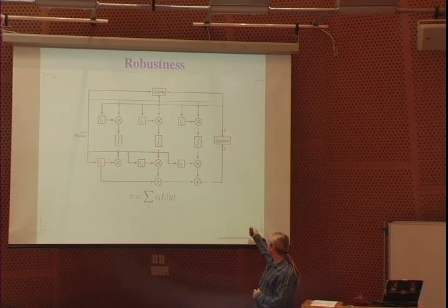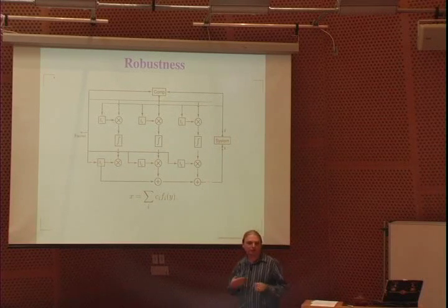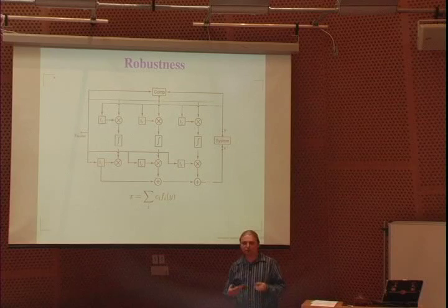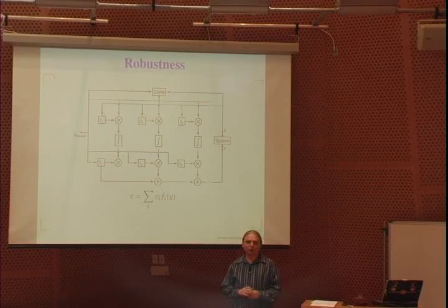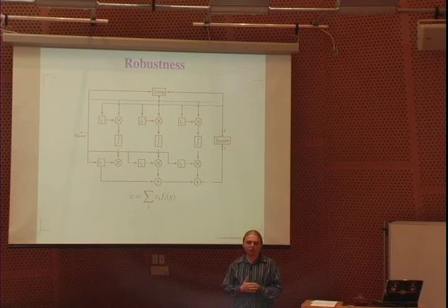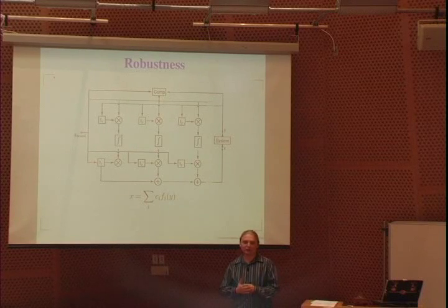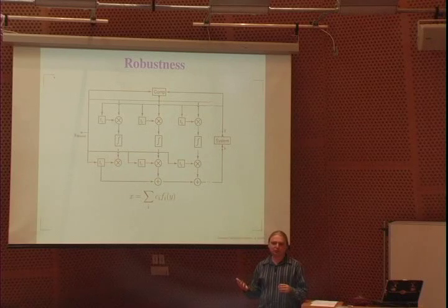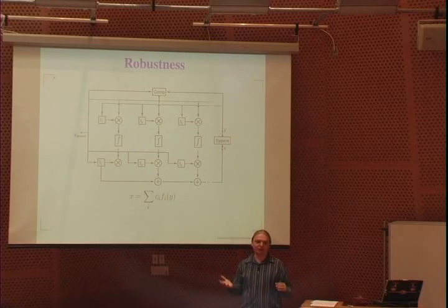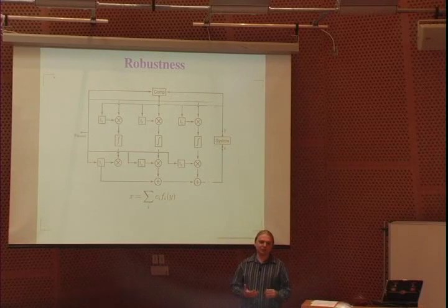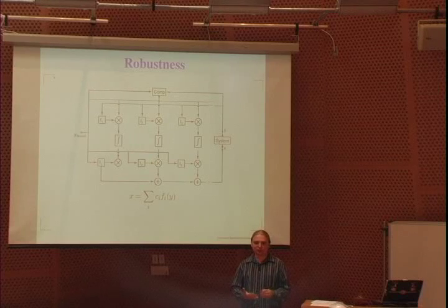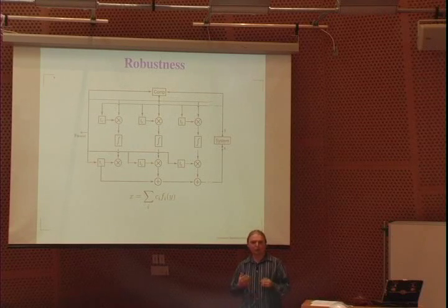They'll just treat that as part of this nonlinearity, and they'll compensate for it, which is a very nice property. In digital circuits, we're coming up with Moore's law to the point where we're expecting devices to fail. So if you look at a device of maybe about 1/10 of a micron, it'll have 150 atoms of dopant in the channel and a standard deviation of 20. As that gets smaller, the number of dopant atoms gets smaller, and we're getting very close to the point where we're expecting some devices to fail.